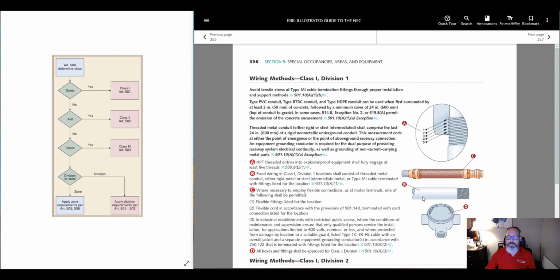This conduit in some installations can be put in as just bare GRC, and in others it needs to be a plastic coated pipe called OCal. That's a brand, but it's plastic coated all the way up to the threads, and then the threads have a special paint on them.